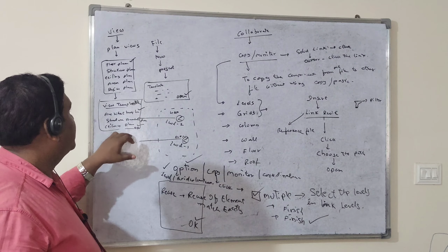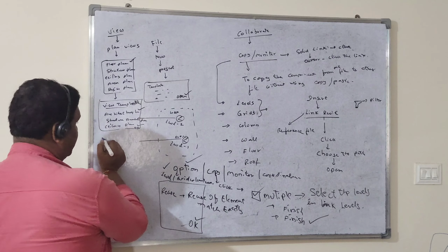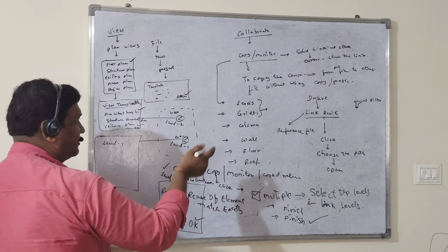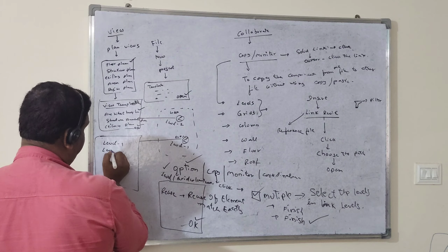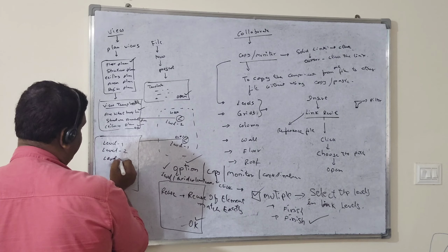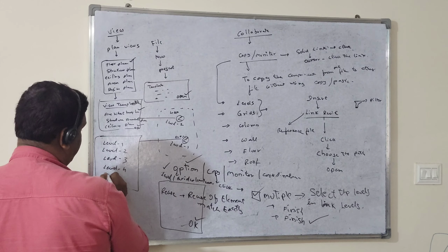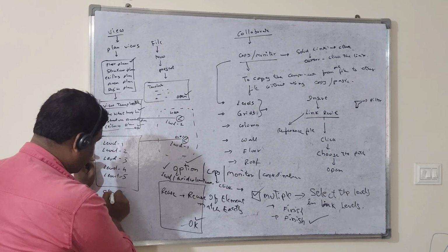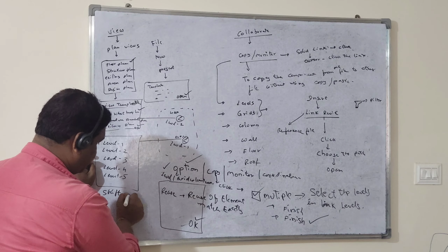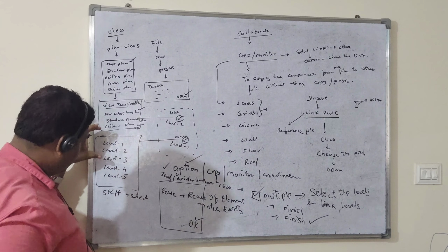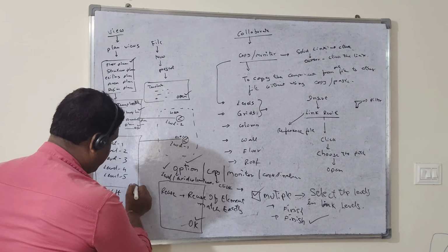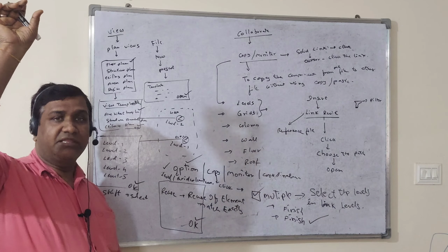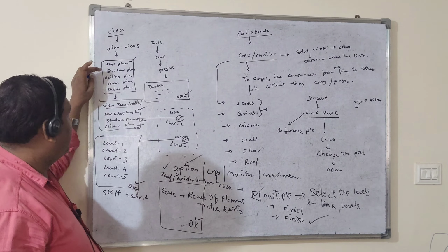After selection of the template, one more palette will be there, and in that palette you will find all the levels are going to be assigned. Whatever levels are there in the reference file, the same levels you will find there, level 1, level 2, like that. However many levels or floors there are, all the floor levels will be found this way. Select with the help of the shift button, shift and select all the levels. After selecting all the levels, you just go with the OK button, then you can find all these levels will be assigned in the project browser with the name of floor plan.